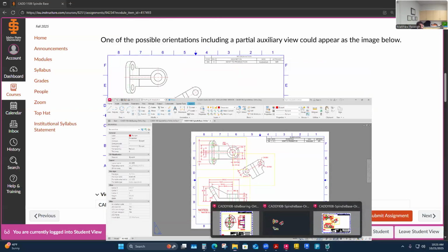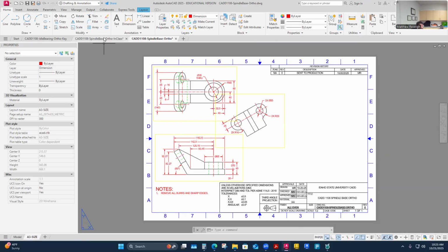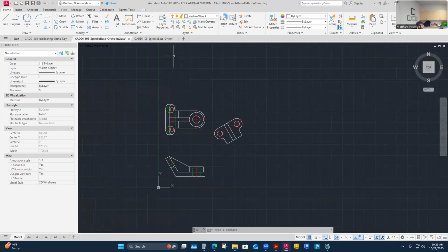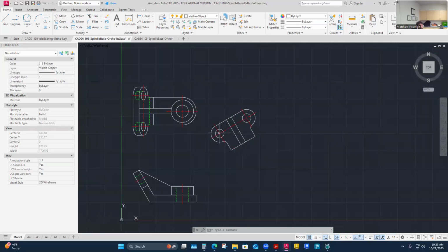The other thing I would wrap up with is, if you're in here, I'll go to the one that I'm drawing. If your view is in, maybe you're dimensioning this, but you're hitting dimensions on this. Yes, you can make a copy of this, slide it up, and then you can dimension it really clean in a viewport where it's not hitting other stuff. Sometimes every once in a while, I make a copy that's clean, but then maybe some of this is still in this viewport that I'm wanting to do.